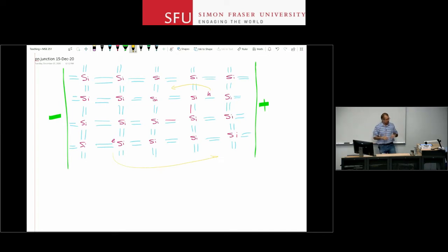So therefore, if you look at this electron, it can jump from silicon to silicon relatively easily, and it is not bound by anything. The hole is not as free to move. First of all, some bond somewhere fairly close to it has to break, and then the electron moves to the empty spot that you had here, and you have an empty spot in the new location. So it's not as agile as your electron in a silicon lattice, at least. It's as if it's a heavier piece. It's going to behave a little bit differently than an electron in a lattice.